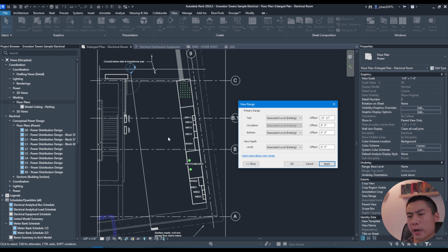I didn't want that up there anyways. So that's your upper boundaries. If you're seeing some weird stuff on the ceiling that you don't want, you can drop your boundaries a little. This probably does not work in an RCP, because in an RCP, you generally want to make sure you catch all the lights at the top of the fixture, or at the top of your space. So for lighting plans, that's usually level above, and you just keep it there.